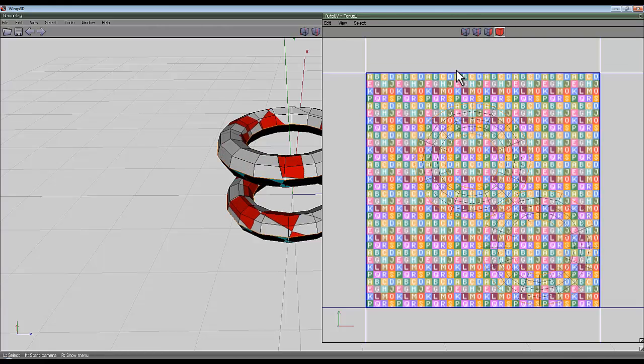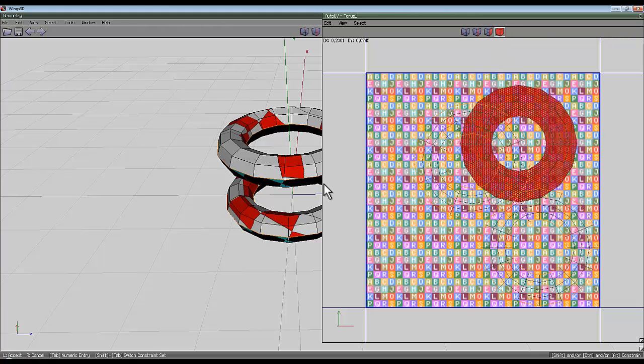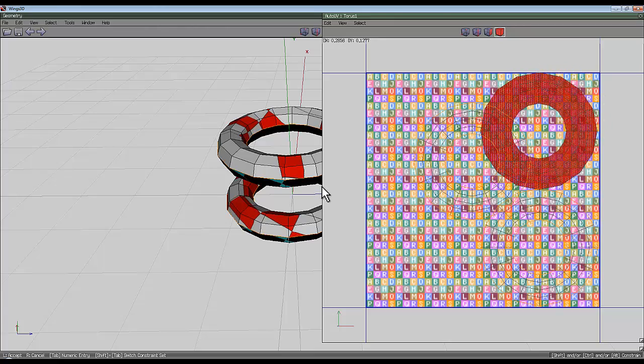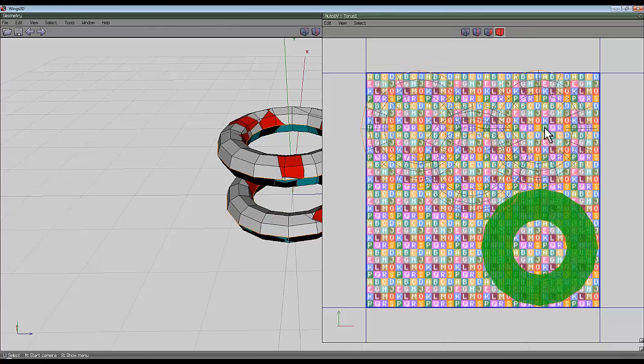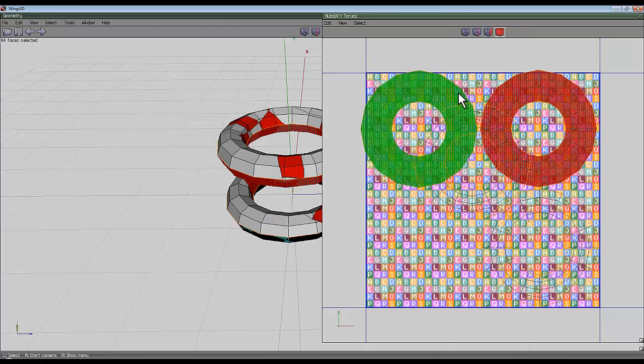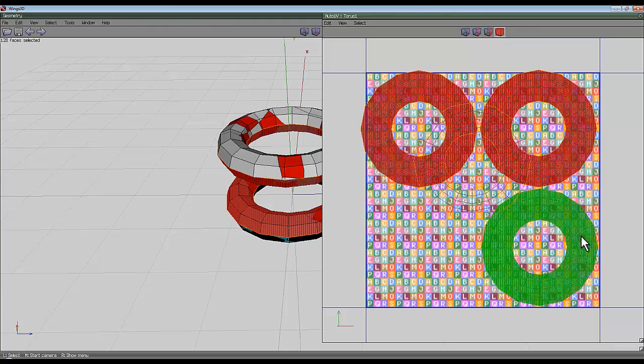It's a little bit fiddly. There's two ways in which this mode works when you're selecting the body, and this is worth knowing. If you've just pressed space and go to body mode, you can drag separate parts apart and they won't stay selected. However, if you select two things like this, when you select a third thing, it doesn't deselect itself. You're now in a sort of different operation. So now it's selecting more and more.